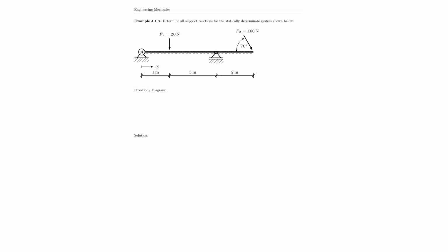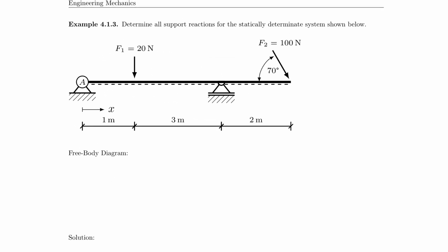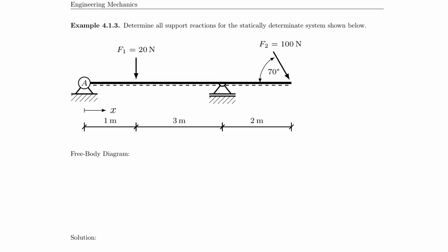So here we have our next fun example, which usually causes confusion in the classroom simply for the fact that we now have a support reaction that sits in the middle under the beam. And please notice this half circle. It's not a full circle that would actually turn this into a hinge, and therefore this part of the system would be unstable if there was a hinge here. So there's only a support underneath it and not in the beam.